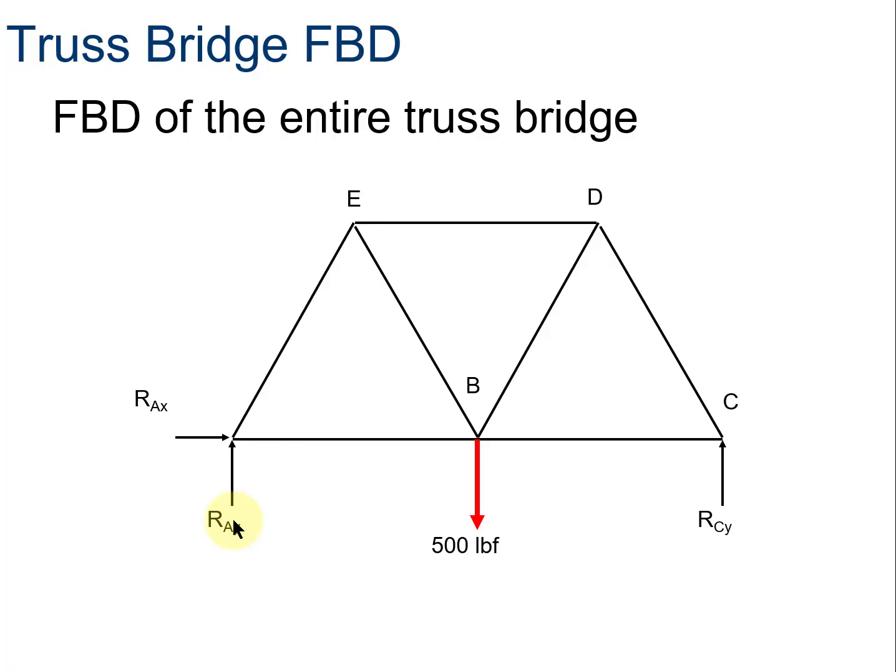So to summarize, what you should have some familiarity with now is what a force is, what a moment or torque is, and, most importantly, what a free body diagram is. Then there are all sorts of specific ways in which a force can be applied to an engineering object, and those were things like a pinned force, a roller force, a tension force, etc. You should be familiar with those, but the big idea is the free body diagram. If you're a little sketchy on that, go back, take a look at some of the slides, and then we'll discuss it in class.